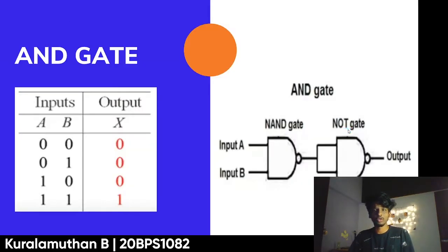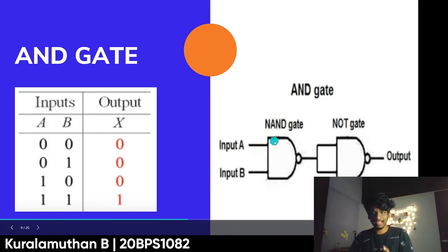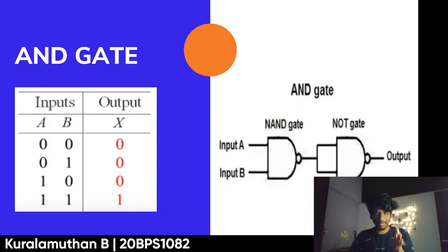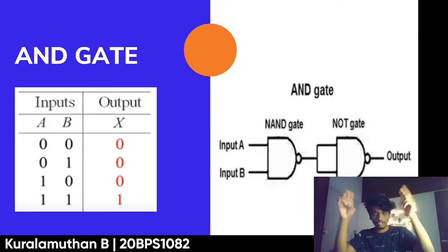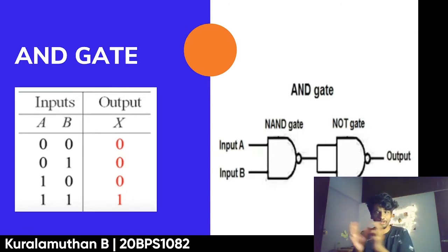Let's go. First we'll be looking at the AND gate. We know that the AND gate can be made using 2 NAND gates. Basically, we'll be supplying the 2 inputs to the first NAND gate, and we'll be routing an output which is going to be (A.B) inverse. Then we're going to supply it to the second NAND gate. We're going to share (A.B) inverse identically to both inputs of the second NAND gate, and it is going to produce an output of ((A.B) inverse) inverse. So the inverse and inverse are going to cancel, and we are going to have A.B at the output.